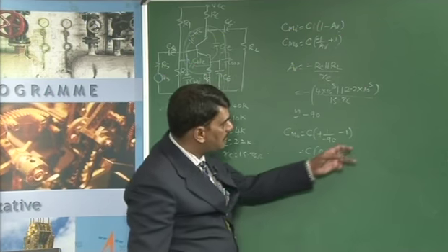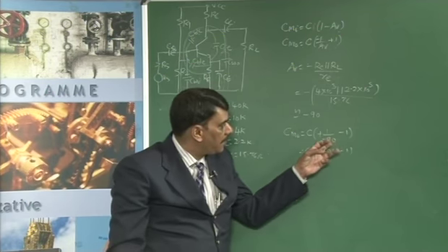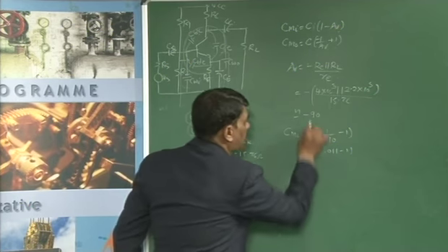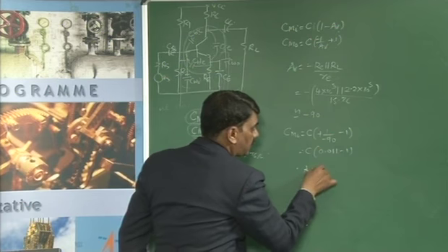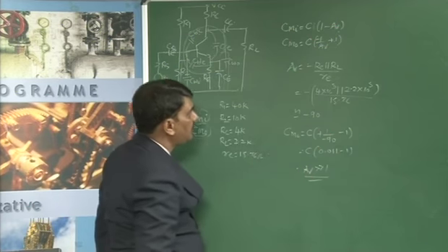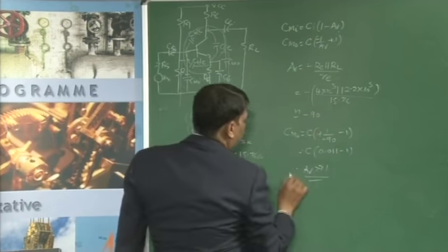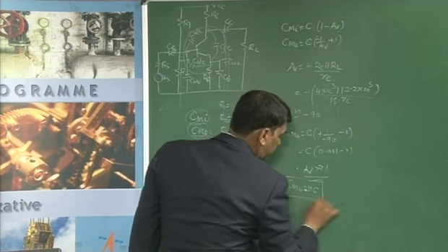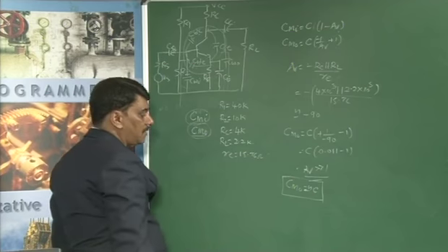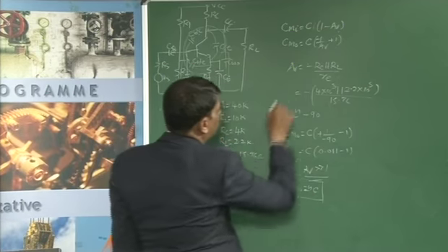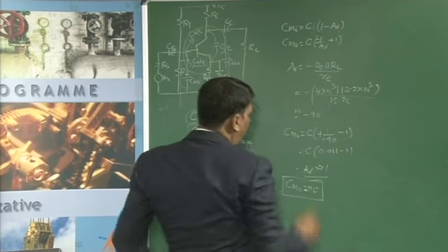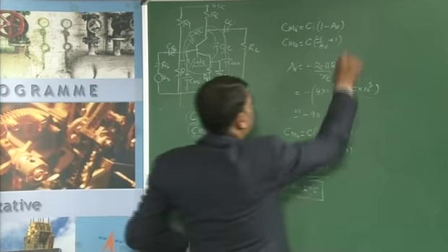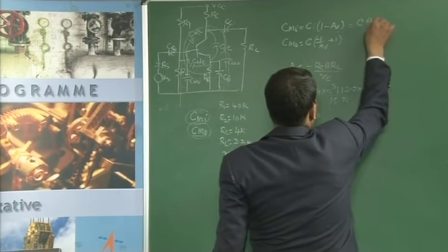When compared to 1, this voltage gain A_V is much higher. Therefore A_V is minus 90, and in magnitude A_V is much greater than 1. Because of this, C_M0 is approximately equal to C. Similarly, R_M0 is approximately equal to R, but C_MI, after calculating the gain of the amplifier and substituting, is about C into 91.